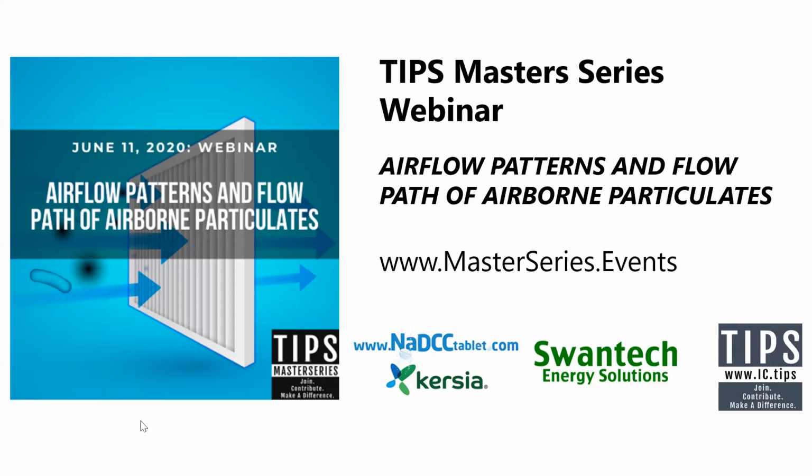Okay. You included an assessment of mitigation strategies if a dental office or a medical clinic, or even a hospital, wanted to move forward with that. What would be the first steps of doing that? The first step would be to lay out the space, find where your supply locations are, where your return locations are. That's the first step. How much air you are bringing in and at probably what temperature, correct?